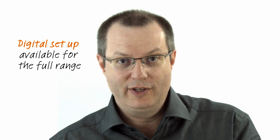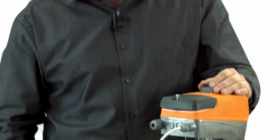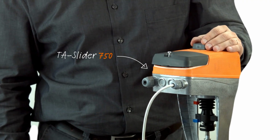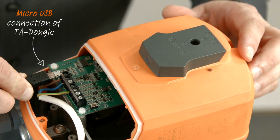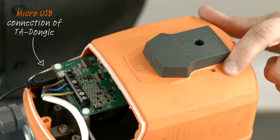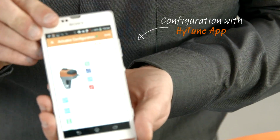The micro USB configuration that we have just seen working on the small range of actuators TA slider 160 can be applied in just the same way on the bigger range of actuators TA slider 750 and 1250. Just open up the compartment, take the TA-Dongle, plug it in the micro USB connector, and as we can observe on the app, the actuator gets recognized by the dongle and by the app. You are ready for the configuration.